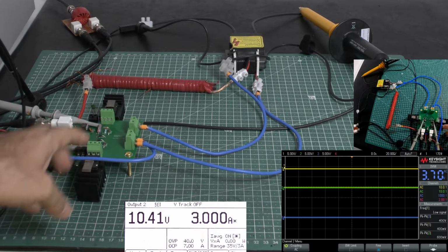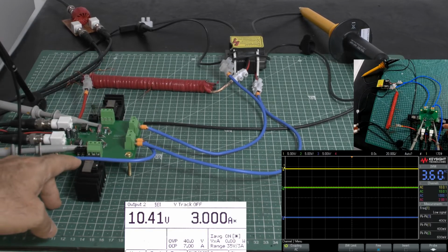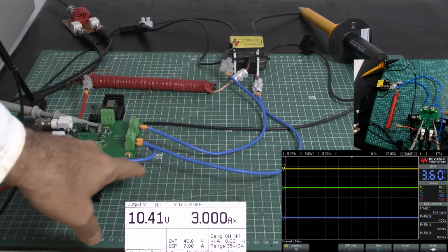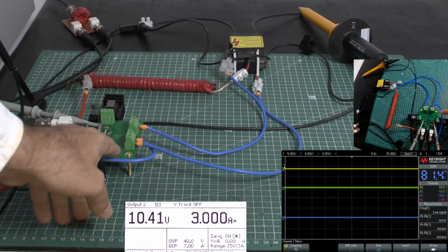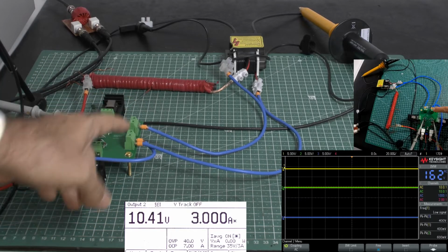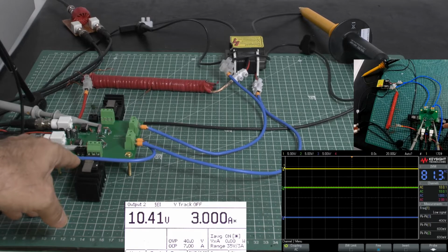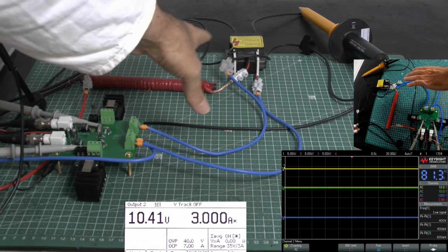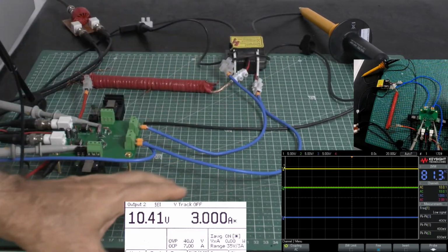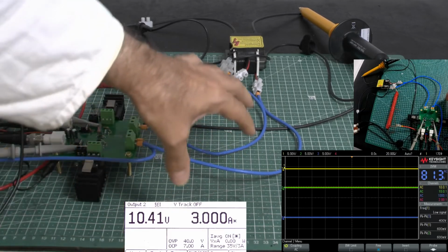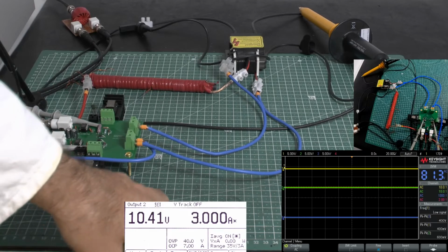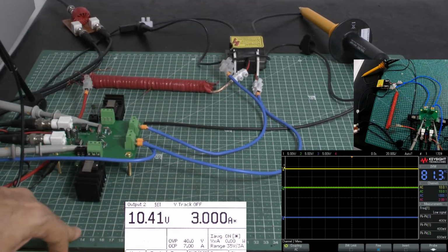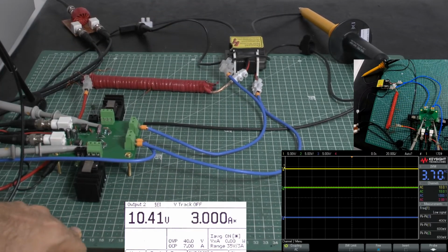Again, I'm using the smoothing capacitor on both sides for only the gate and not using an RC snubber circuitry on top of that, because I'm getting much more efficient results like that. I take care of the other issues with components outside, or I use an external regenerative device or circuitry to allow for smoothing of the signal.